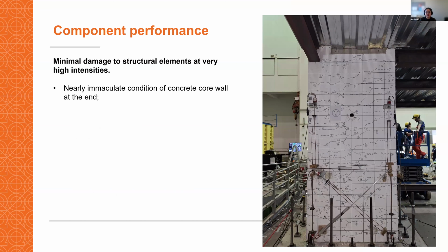We ran many shakes and induced a very heavy intensity. But even with that, very minor damage to structural elements was observed. Specifically for the concrete core wall at the end, this is a photo of its cracking map. As you can see, there's no crushing of concrete and no wide cracks on the concrete core wall. So the concrete core wall at the end of the test is in quite good shape.